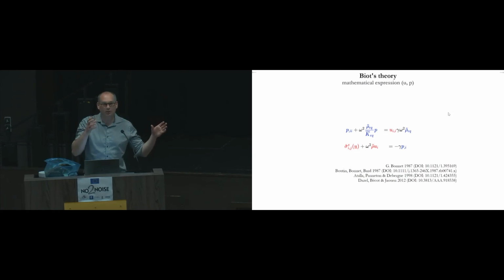The first one we compute without dealing with the elastic skeleton. Okay, we compute rho and k. So with the pore size morphology, we get this. We put this in these equations. We solve these equations. And we get the motion of the wave propagation in our porous materials with an elastic skeleton.